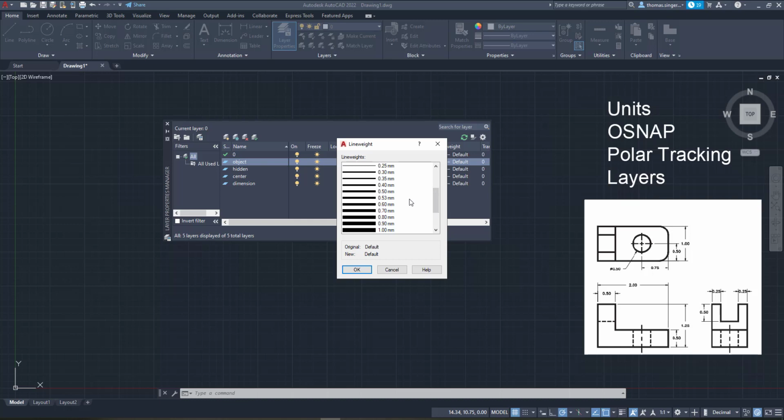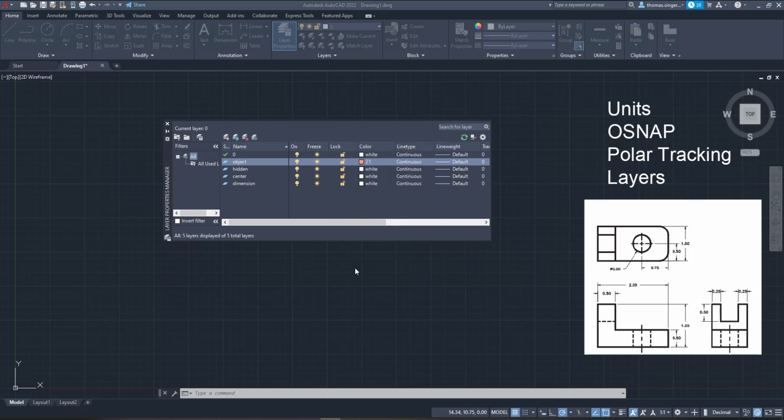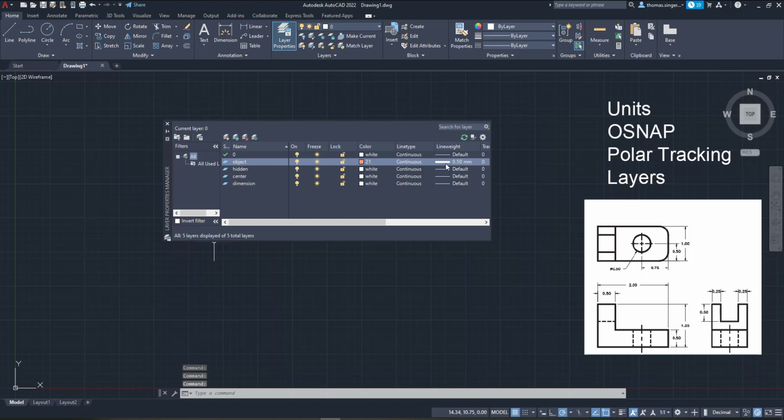Well, if you've got a mechanical pencil handy, if you take a look at the side of the mechanical pencil it has a number. A lot of times it'll be like 0.5 millimeters or 0.7 millimeters. And it's the diameter of the lead for that pencil. And that's exactly what this setting is. This basically sets the diameter of the lead, or the thickness of the line, based on the same type of settings that you would have with a mechanical pencil. So setting it up as a 0.5 is perfect. And so it'll be a slightly darker, thicker line if we go to print this and set that up that way.